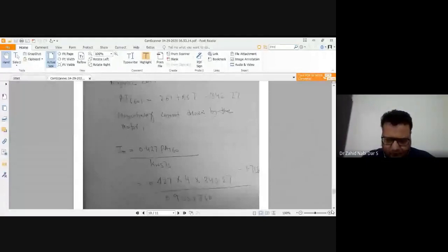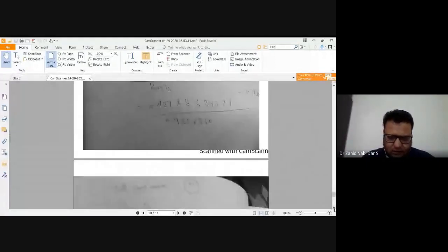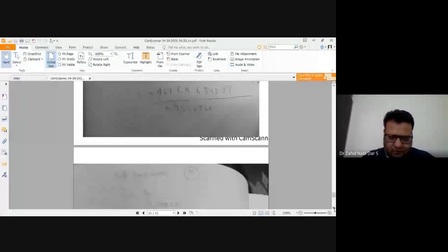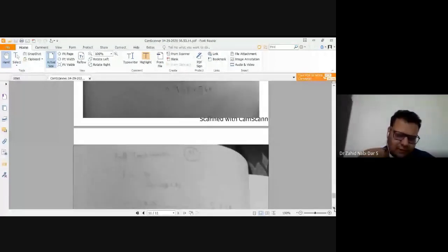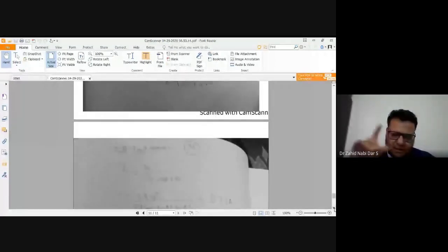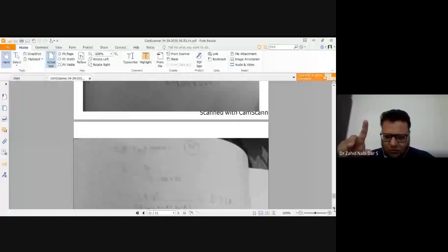And now your full load current. See, the formula for your current is your power, 3 times Es I cos phi into efficiency is the output power. If you need the current from that formula, you can write Is is equal to P naught divided by 3 Es cos phi into efficiency.